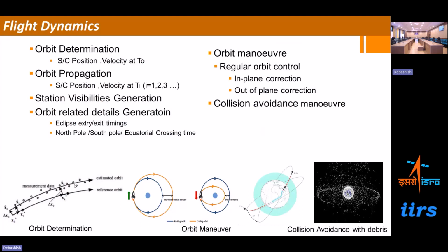So we have to remove the noise. Then we have to finally go for a particular time t0. What is my position? t0 talks about the epoch time. At a particular t0, what is my position or velocity? You can think at t0, we will try to find out p0 and v0. That is, at a particular t0 location, what is my position and velocity. From the measurements, I am trying to define the initial condition. So that is called the orbit determination.